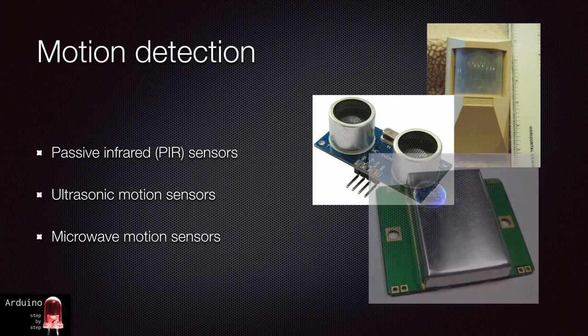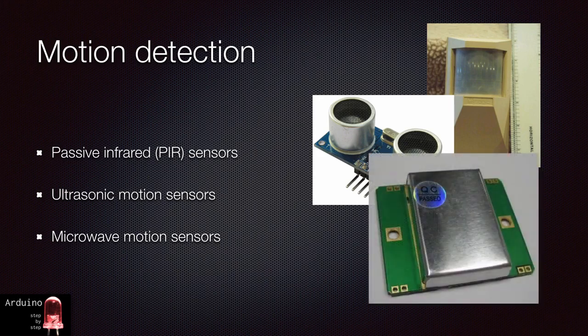A microwave motion sensor works on the same principle as the ultrasonic sensor, except that instead of ultrasounds, it emits microwaves. They are still relatively cheap, and because microwaves are much higher in terms of frequency than ultrasounds, motion can be detected with a lot more detail. Many microwave motion sensors can determine not only the motion itself, but also distance and speed using the Doppler effect. This is an example of what a microwave sensor module looks like. Of course, the module is covered by a plastic cover when installed.